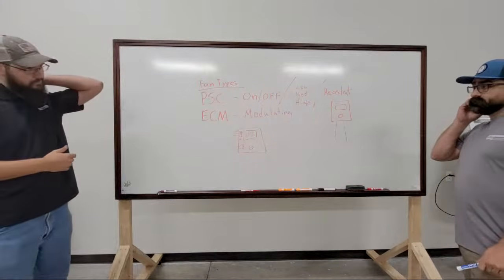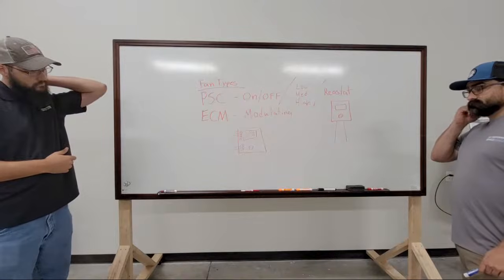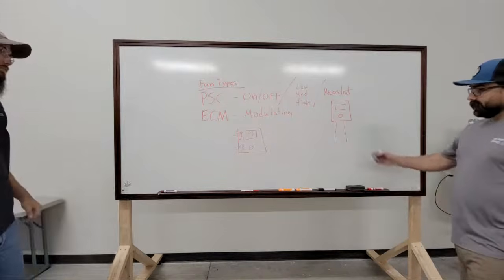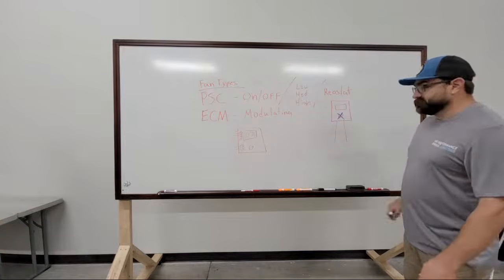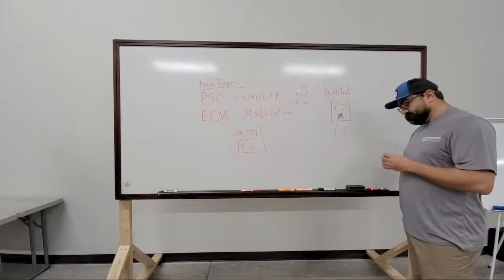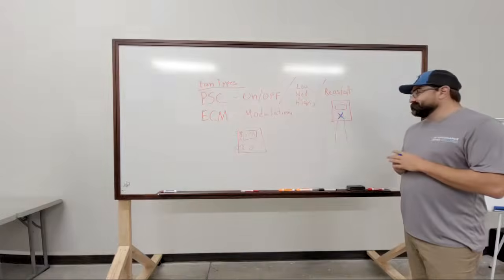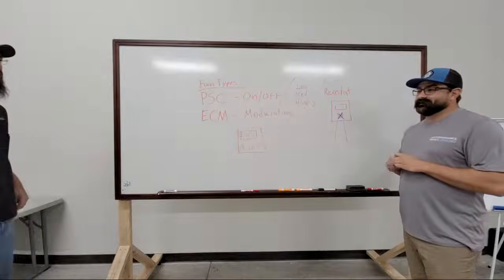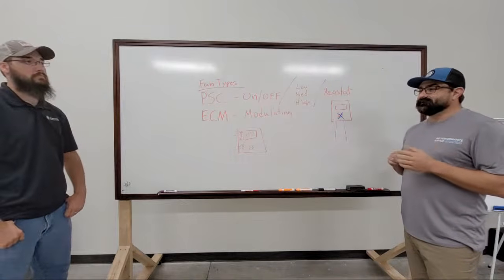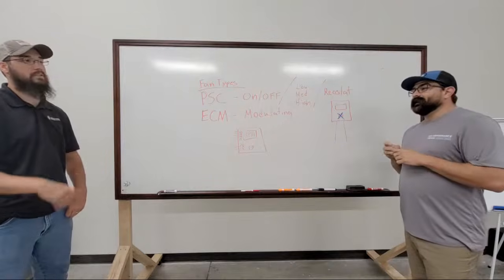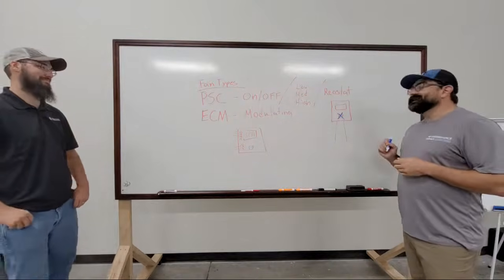Yep. So one thing to mention, personally, I don't ever recommend touching these. They're set through test and balance. If you touch them, then that balance is no longer valid and should technically be redone. Until you have to replace it. It's getting there.